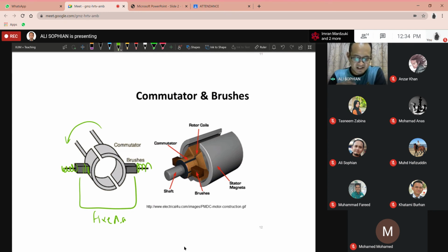And this is actually the weakness of DC machines, because of these brushes. Every time the rotor rotates, there's friction between the brush and the commutator segments, and the friction removes bit by bit part of the brushes, and the brushes get shorter and shorter until eventually it will stop working. This becomes the weakness of DC machines.